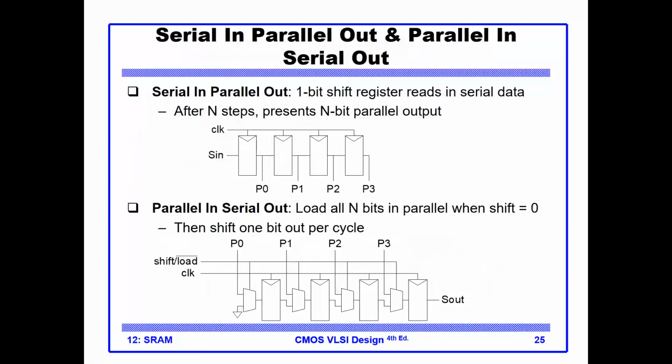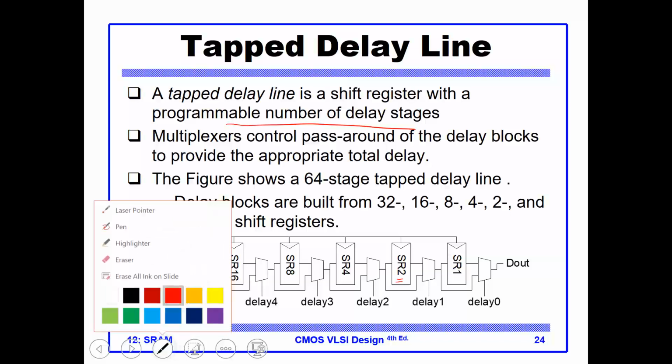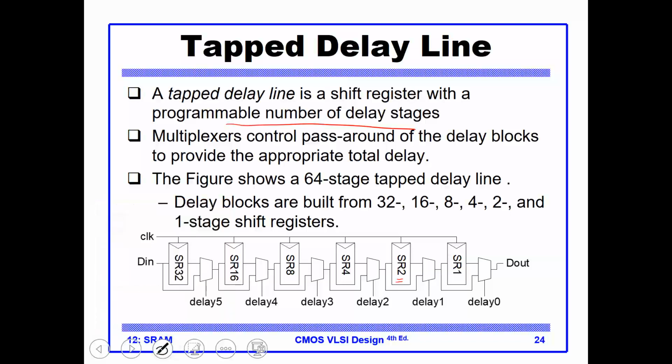So to delay 3 cycles, what do I do? I activate this control signal, and I activate this control signal, and deactivate all the others. So what happens is that the data will bypass this, and then bypass this, and it doesn't wait. Then it comes here. It has to go through this because the control signal will pick it. So 2 cycles delay, then it comes in here. It has to go here because the control signal is active. 1 cycle, 2 cycles apply.